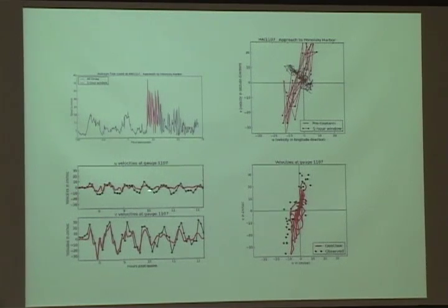The black curve is the U velocity, and down here the V velocity as measured at that gauge, and the red curve is the corresponding measurements from the GeoClaw model. So even for the velocities, one can get fairly good accuracy out of these sorts of models. And this is the same data looked at in the UV plane, so that you can see that in addition to the amplitudes being about right, the direction that this wave is coming in was also about right.